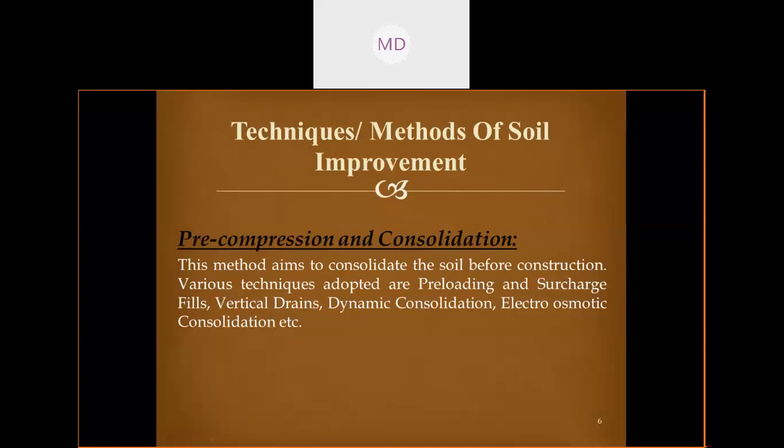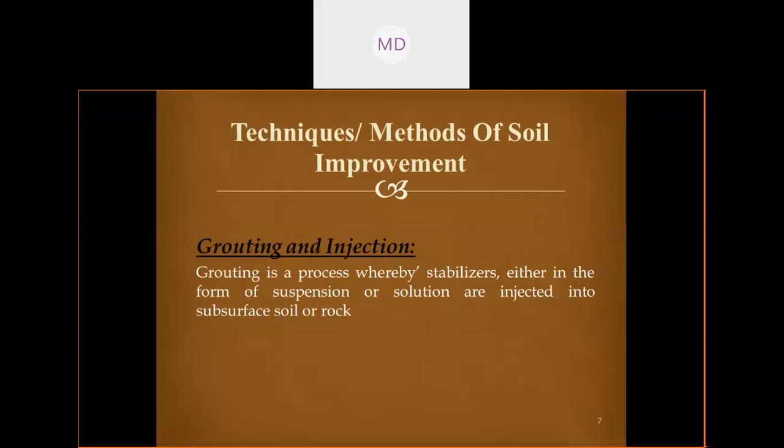So if we combine preloading and vertical drains, the process becomes a bit faster. Then dynamic consolidation, I have already told, is applying heavy loads. And then next we move to grouting and injection.